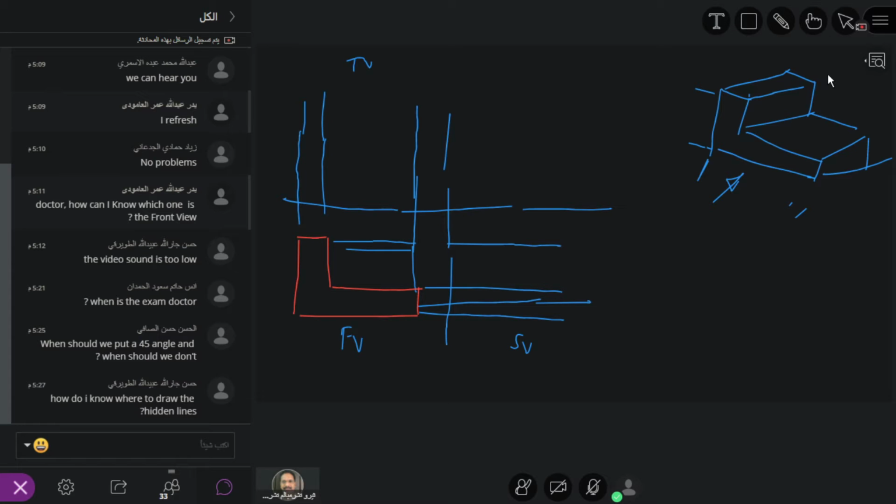So now when I see from the top view, this is the first surface I could see. So first, when I see from the top, this line is there. So I draw the same extension here by keeping the same distance, and then this is the top surface, this surface. Okay, this is this surface, and then I can see this surface. So I will extend this, I mean, draw this here, and that's it. So this is my top view.